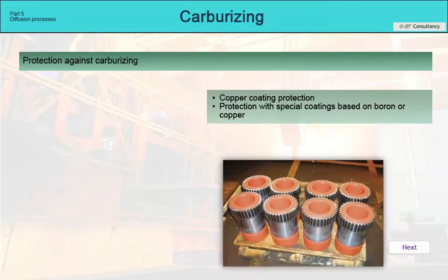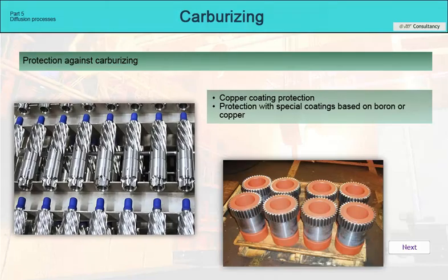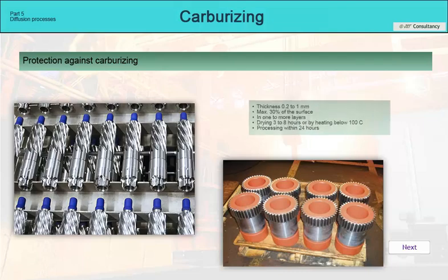However, it is necessary to distinguish the type of paint material because, for example, those containing copper are not suitable for carbonitriding due to a possible reaction with ammonia. On the other hand, pastes containing boron are now considered toxic substances and therefore require special treatment. For this reason, they can be considered in special cases.